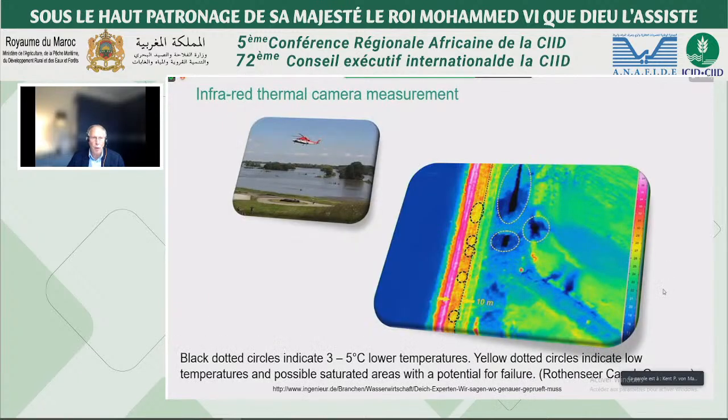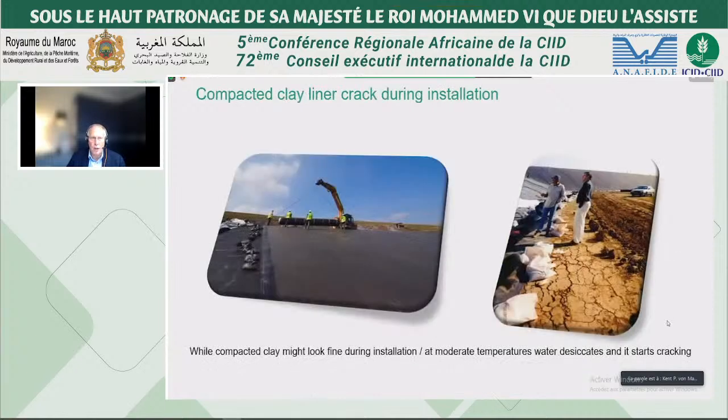And in the meantime, we have measurement systems where you can measure these in advance, like you see from the helicopter. They do infrared thermal camera measurements, and they can locate the weak spots in the dam so that you can already prepare yourself and start either evacuating people, or better, of course, start repairing these areas with maybe solutions like geosynthetics.